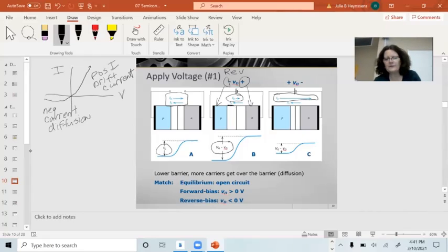And the net effect is I actually lower the barrier height by whatever V diode is. If I get to the point where the voltage across the diode equals V0, you achieve a flat band, where you get a flat voltage across the whole thing. Current can flow freely, like it's a short circuit. Many, many ways to describe how a diode works.